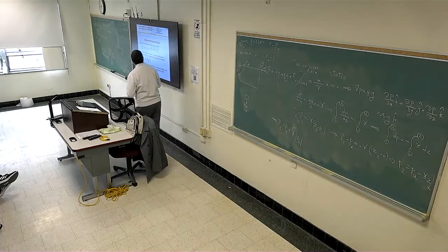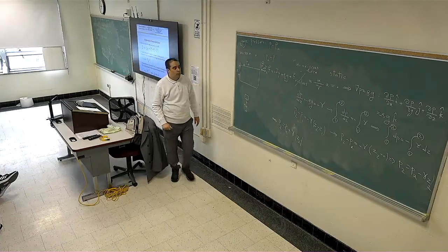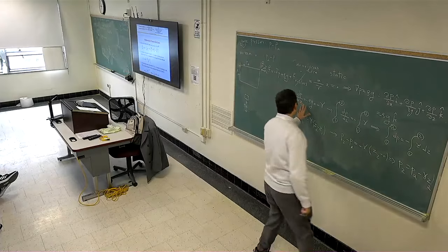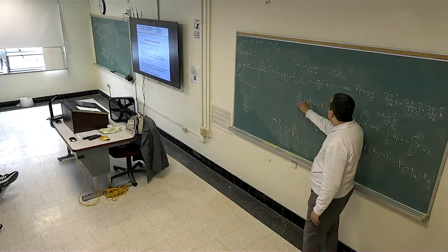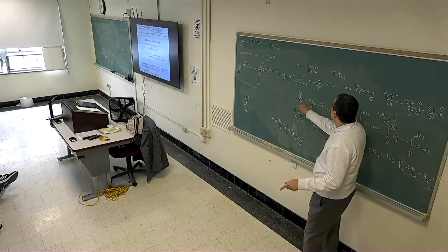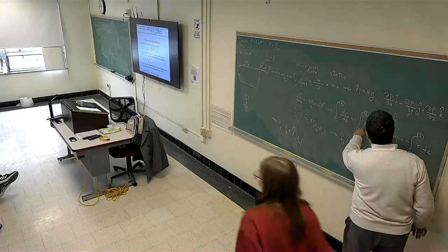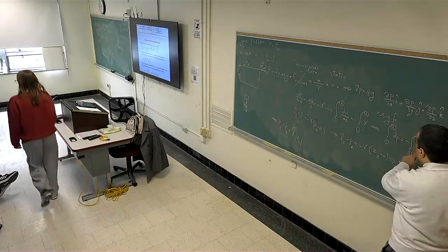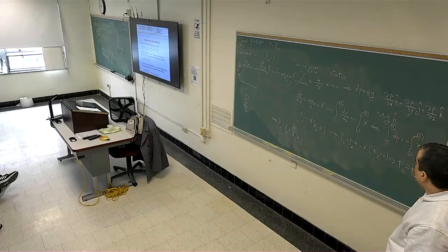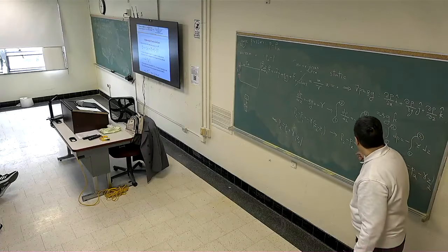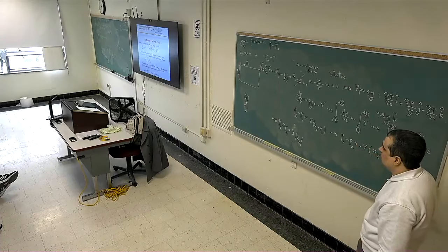For the gases, if we go back to our equation, pay attention, it is our equation. dP/dZ is minus rho g, okay? For liquid, we assume rho g is constant. So we take gamma out of the integral. Gamma is independent of z. We take gamma out of the integral and you see gamma is constant, delta z is z2 minus z1.